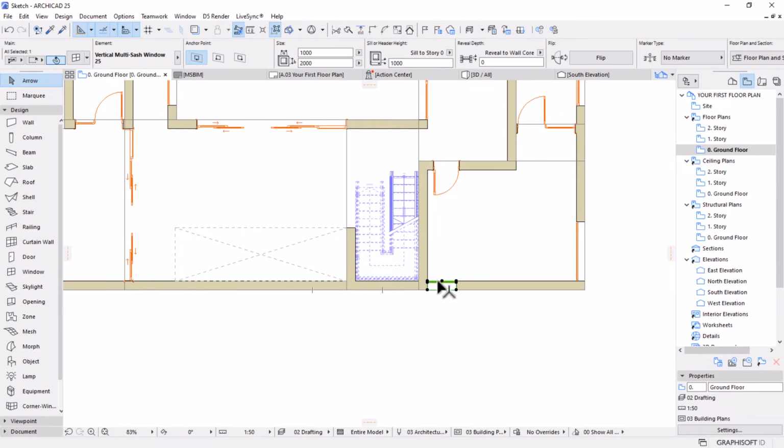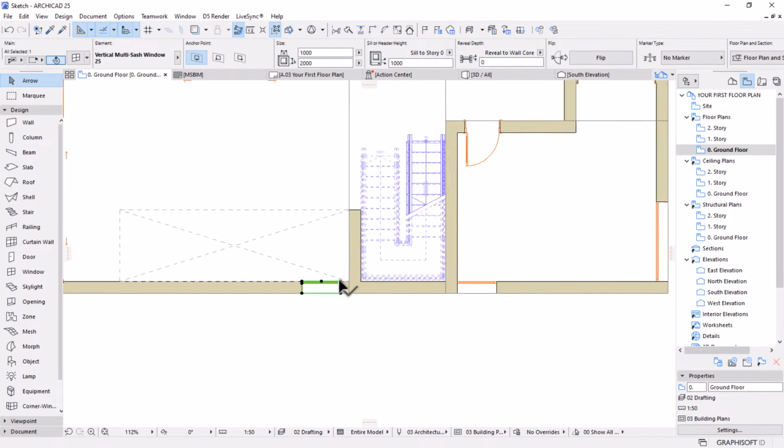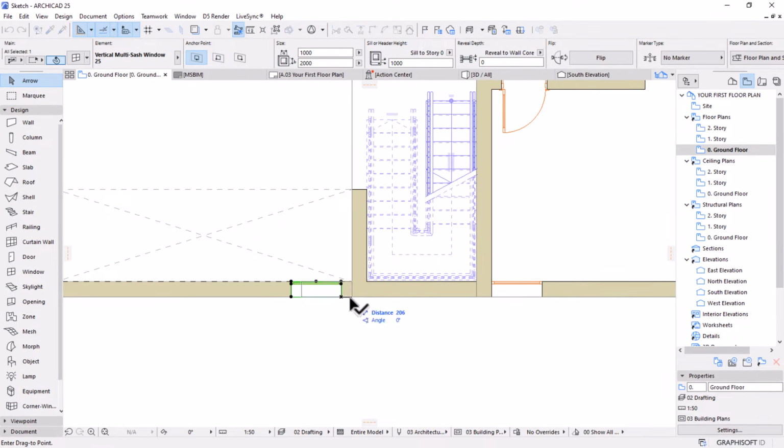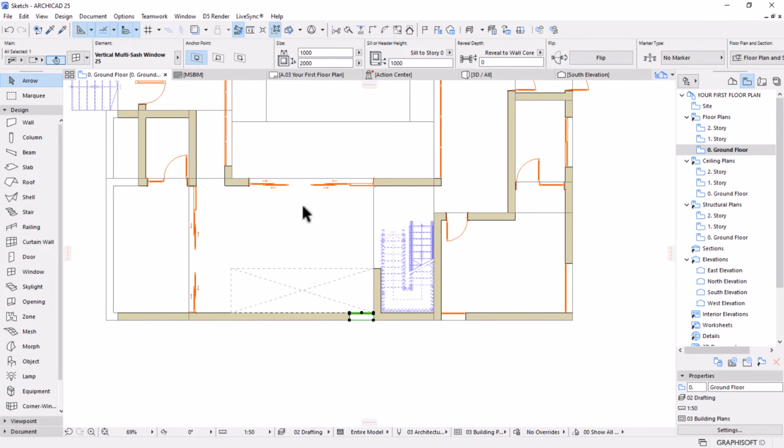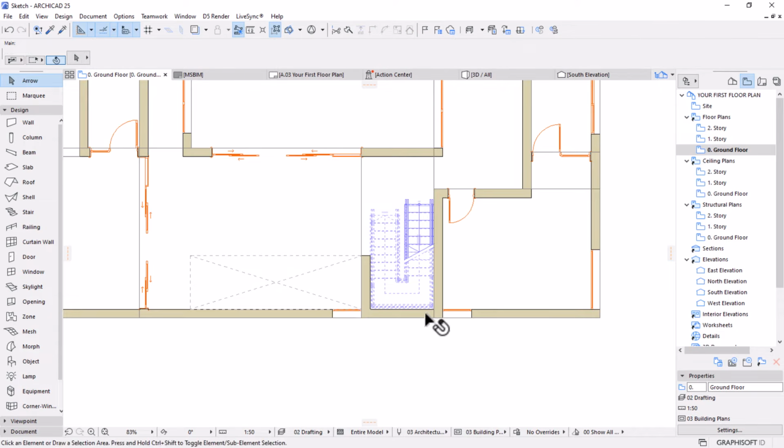I can repeat, maybe take this and then Control Shift D to carry a copy, or you can move this by picking one of the points here and then use drag. If you drag while you are still in the operational mode for dragging, you can hit Control to add a copy so that you can place it right by the corner here, just to have a window here by the void of the lounge. Okay, so we have another one there.